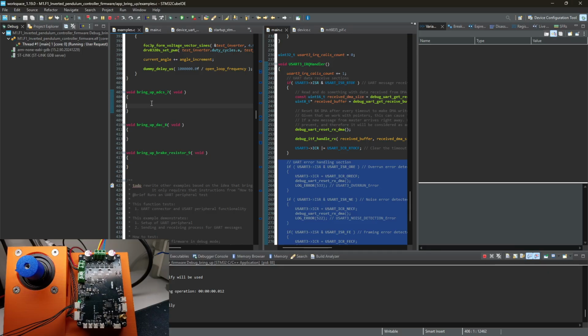Because for the perfect FOC, you would like to measure your phase currents at the same time in both channels. You don't want to measure them one by one because you will have an error. And you will have lots of error for many reasons, but this one is quite a big reason for errors. So you want to measure at the same time. And for FOC, you would like to spend, like, let me actually draw it real quick.